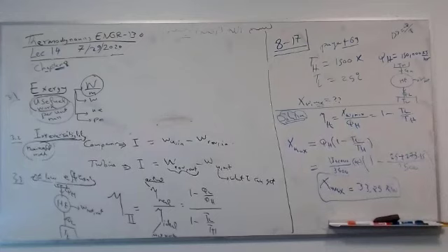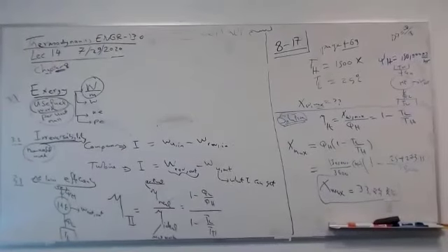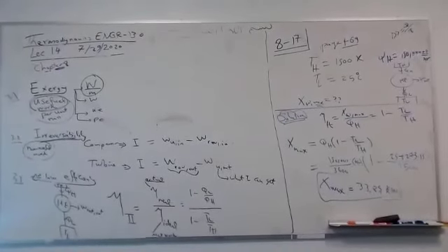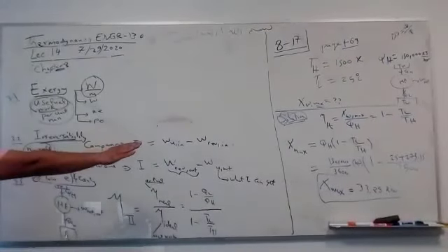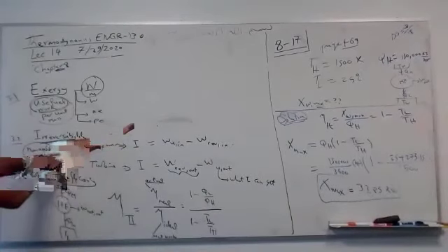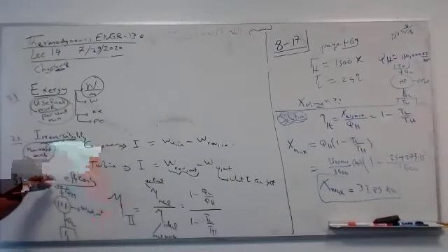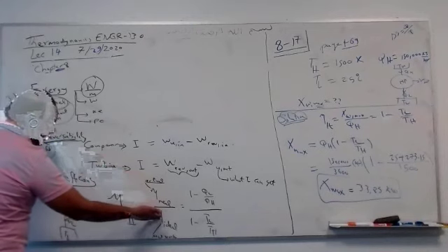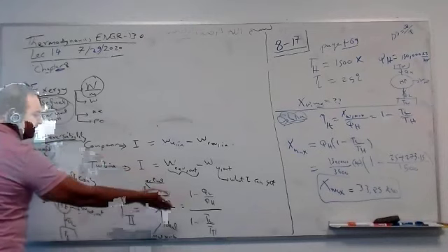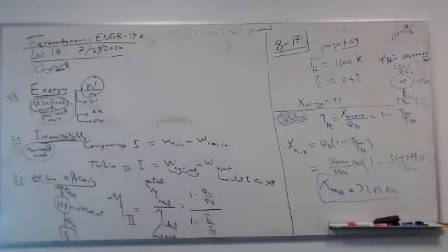If it's at max, does that mean there's none? Exactly, zero. Irreversibility is zero. Second law efficiency, 100%. That's it. So you have zero non-useful work because you are working at the maximum operation. I did not give you Q low, which means irreversibility is zero. So simple, guys. Second law efficiency is 100%. Actual over ideal, it's exactly ideal. So it's 100% efficiency. I'm operating at the maximum performance.